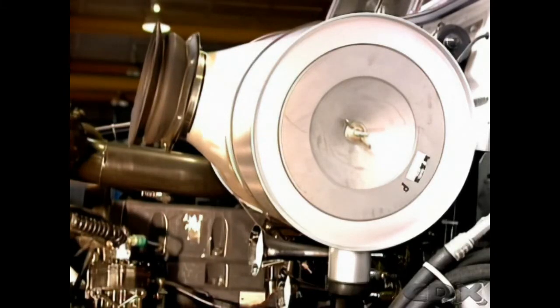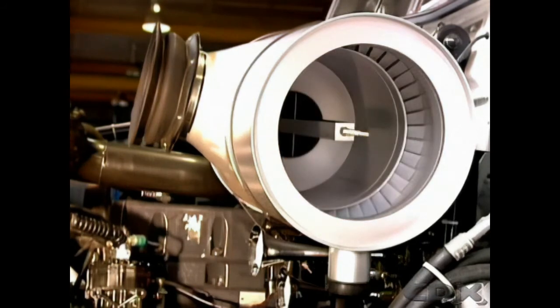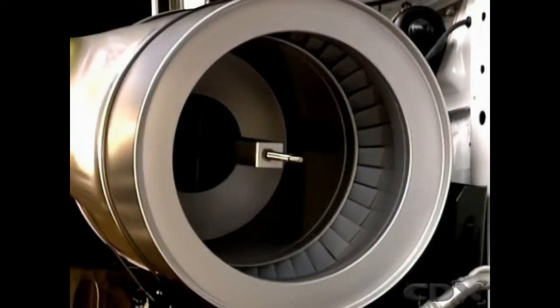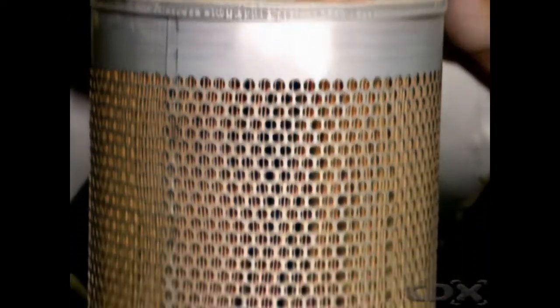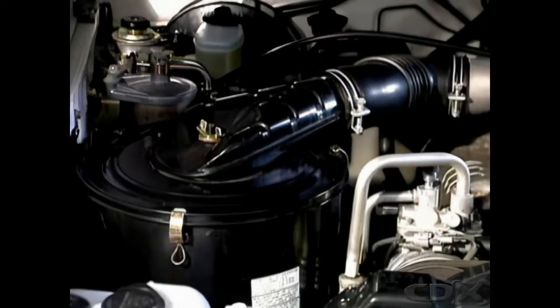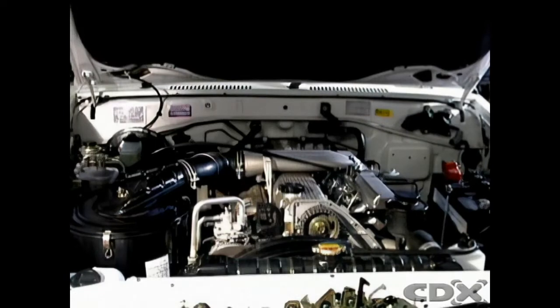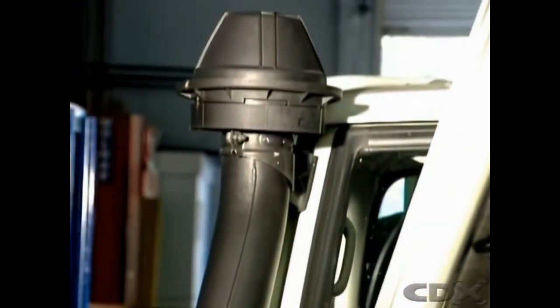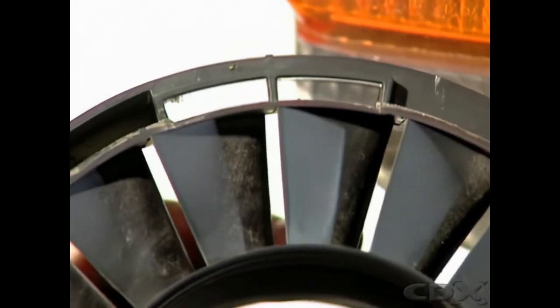Most heavy-duty air cleaners incorporate a cyclone-type pre-cleaner. It collects larger particles from the air before it enters a dry element cleaner. It can be mounted directly onto the air cleaner unit, or the cyclone principle can be incorporated into the main air cleaner element. This dry element cleaner is fitted close to the engine, and it's linked to the cyclone system by a duct. The name cyclone comes from angled vanes that give the incoming air a swirling motion.